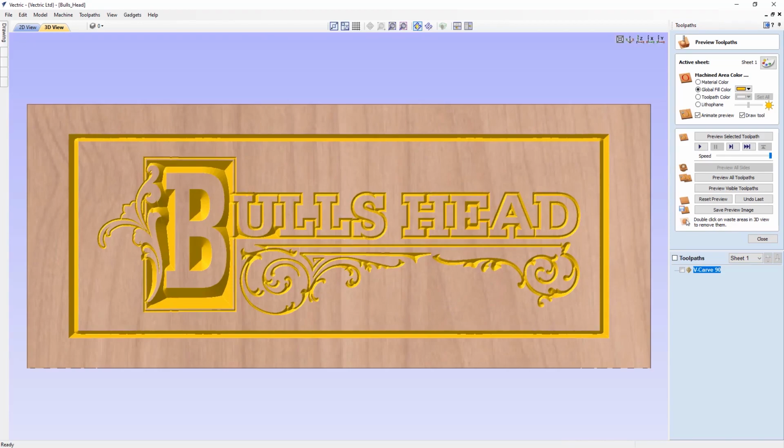So even though we are explaining the steps to create this sign in a lot of detail, you can see how quickly it is to open the vector file, alter the job setup, select all of the vectors and center them in our job, switch over to the Toolpath tab, double checking our material setup, creating the toolpath, calculating it, and then previewing it here. And we could have, in theory, got this to this stage within 1 minute of starting.